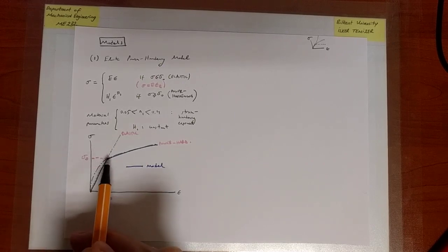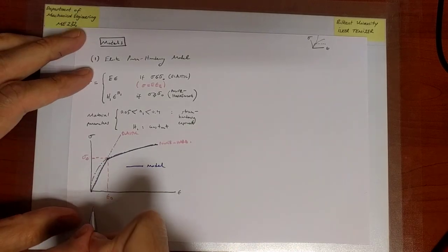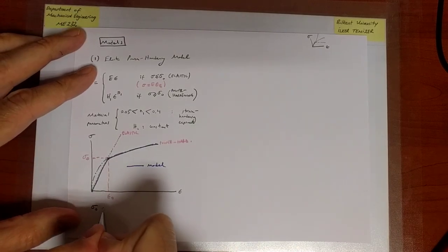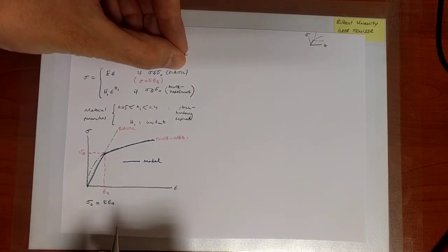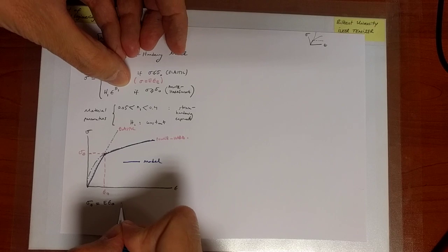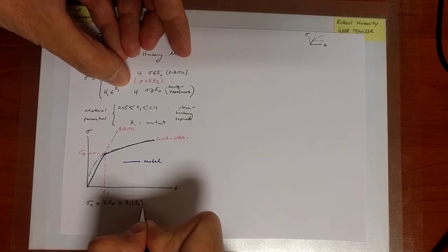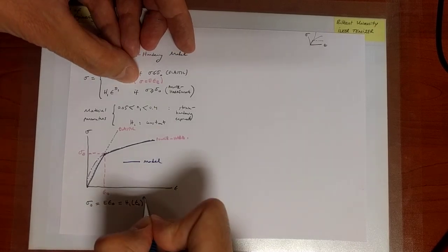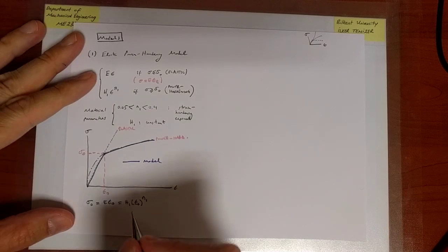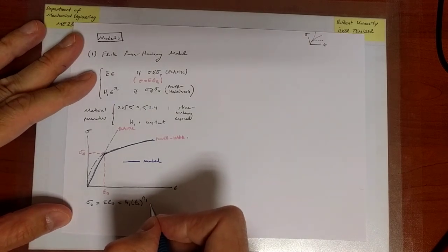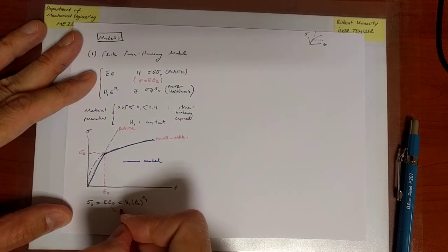Well, now that gives us an idea about how to calculate the yield strength. The yield strength, sigma naught, can be predicted in two ways. One, it is equal to E times the strain at yielding, that's the elastic portion of the curve, but also the power hardening relation is supposed to give us exactly the same value. Epsilon 0 to the power n1 is supposed to give us the same value of stress. And from these relations, what you can do is first of all solve for the value of epsilon 0.